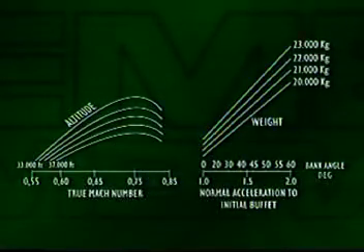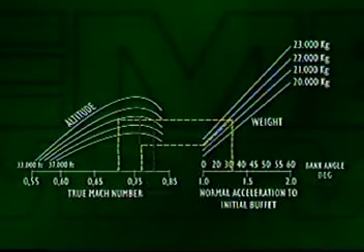This is a chart documented in the approved AFM, which shows the low-speed buffet induced by stall and the high-speed buffet induced by the shock waves. Also, you can get the normal load factor or bank angle to buffet at a given Mach number, or the altitude margin at a given Mach number and 1G.